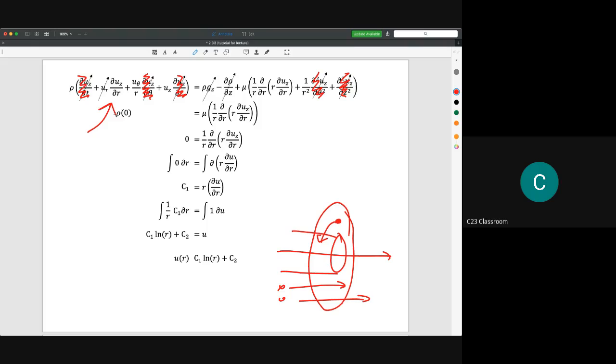Please make sure that, as I explained previously, the velocity in terms of the r axis here changes because of the no-slip condition and so on and so forth. So the du/dr here will give you a certain value, but the u_r here is 0. The u_r means the element of the molecule moving in the r direction.